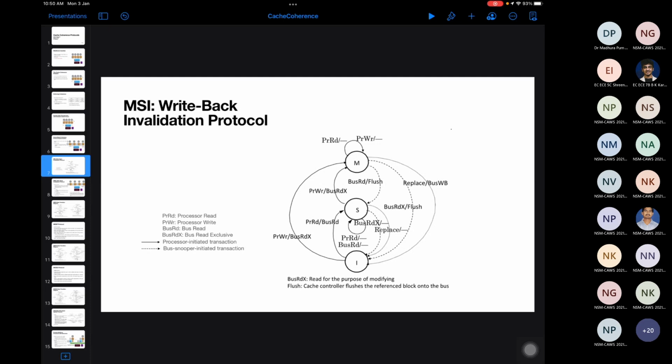They'll see that there is a read request from someone with this particular address, and everyone is going to search in their caches to see whether they have the data in a modified state or not. If any of them have the data in a modified state, that particular core is going to respond. If no one has the data in a modified state, then automatically the lower level cache, that means the L2 controller, is going to see this transaction and place the data.